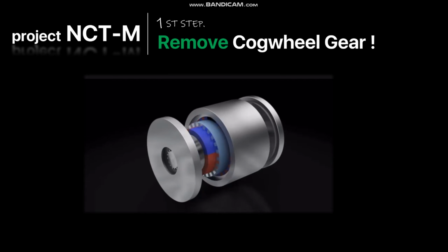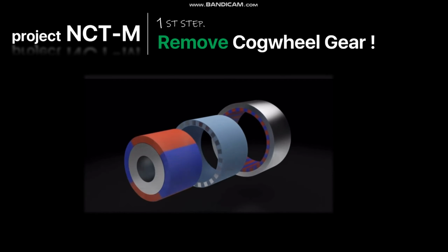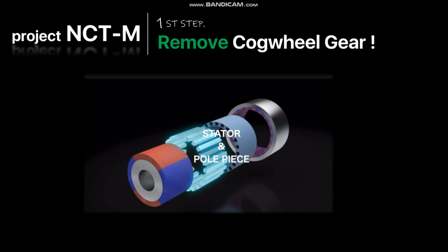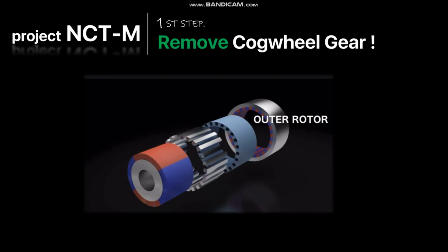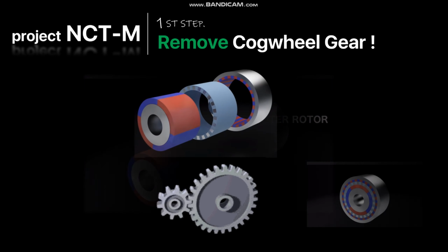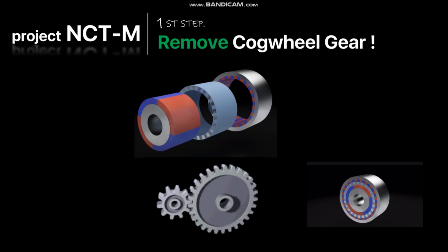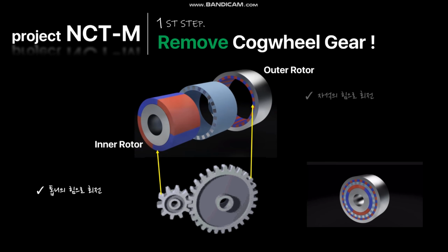It has a very compact size and consists of 3 parts: inner rotor, stator and pole piece, and outer rotor. I'll compare this with cogwheel gears for understanding. Inner rotor is the small gear of the cogwheel gear, and outer rotor is the large gear of the cogwheel gear. Cogwheel gear turns by the power of cogs contacting each other, and magnetic gear turns by the power of magnets.